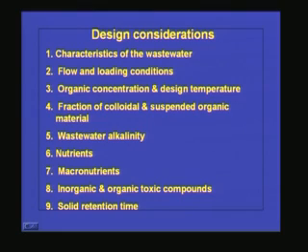What are the design considerations whenever we talk about the anaerobic process? It is almost the same as that of the aerobic process. We should know the characteristics of the wastewater, because that defines what type of treatment or how much time is required, etc., and flow and loading conditions, organic concentration and design temperature, fraction of colloidal and suspended organic material, wastewater alkalinity, nutrients, macronutrients, inorganic and organic toxic compounds, and solid retention time. So these are the design considerations for any of the biological systems we have already discussed.